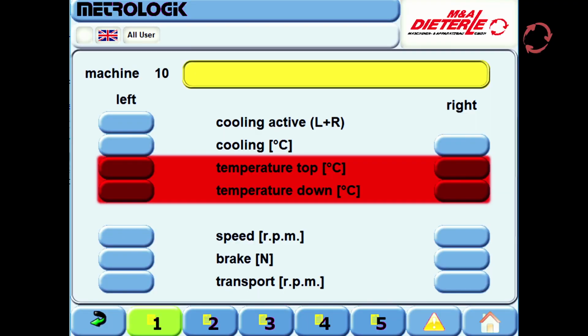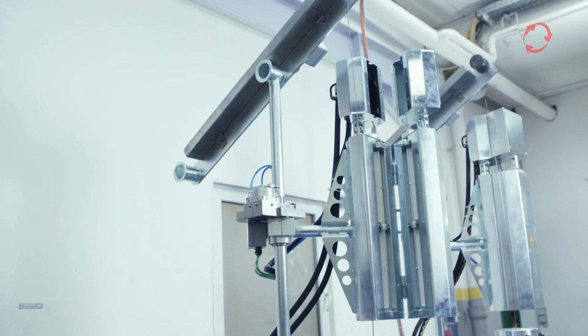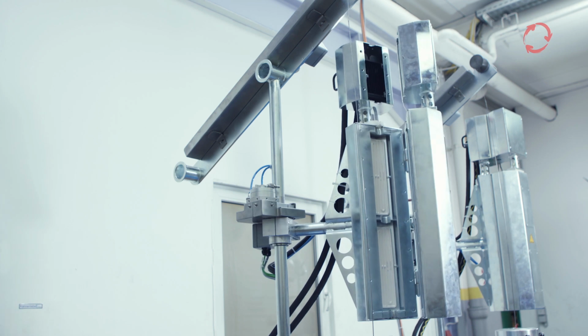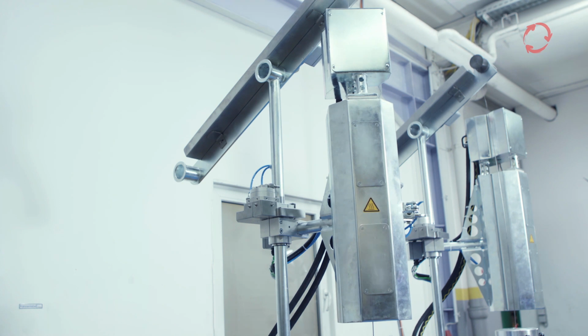The temperature must first be set in the process parameters of the respective program. This is described in Chapter 2.4. The heater, which is still in neutral position, is then pneumatically opened, pneumatically pivoted to the spiral mandrel, and closed again in that position. The heater now surrounds the spiral mandrel with the spiral feeding in from below during the winding process. The heater's motion sequence is controlled manually with the buttons on top of the machine.